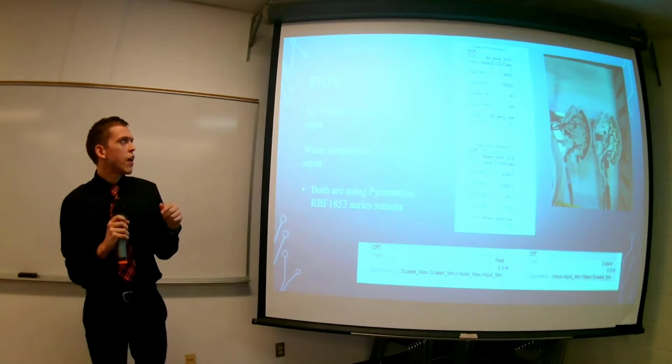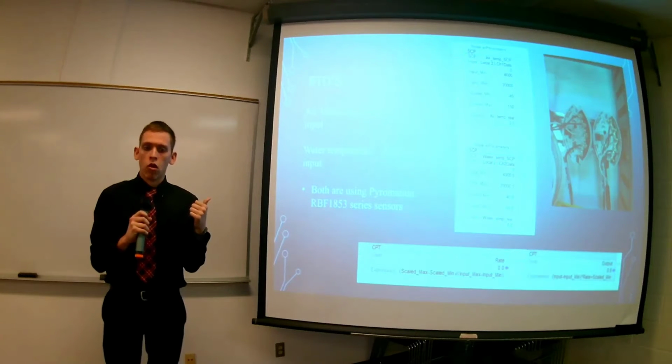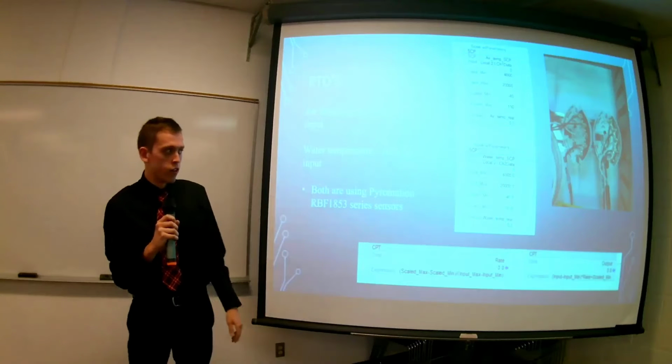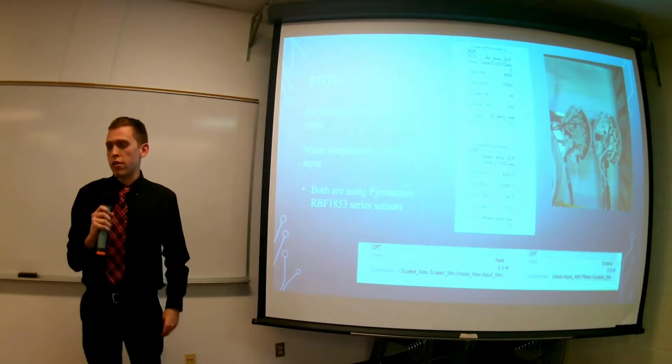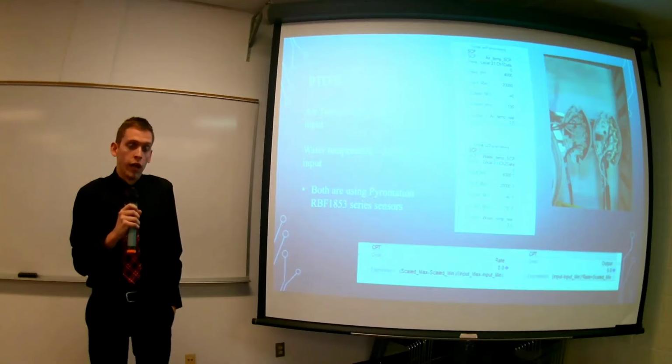And then we also have air and water temp being measured as well. So we are using RTDs. Those are the transmitters up in the right corner, if you could see those. And then we also are using the scale with parameter instruction to be able to scale that raw data value into something we can understand.